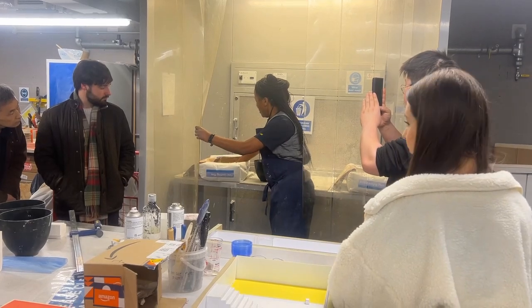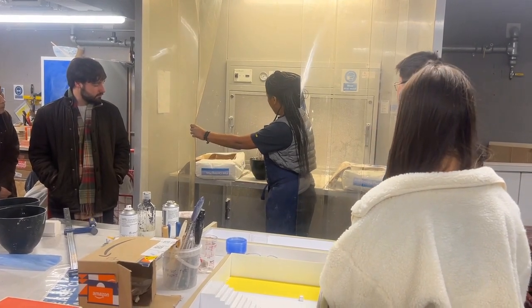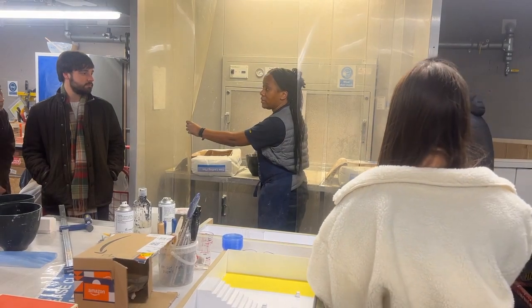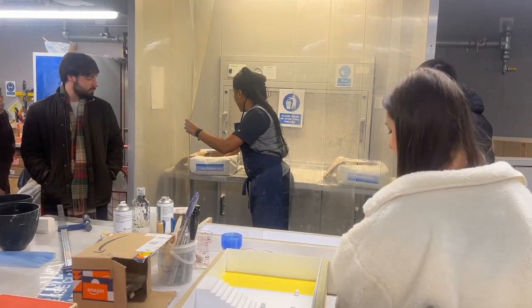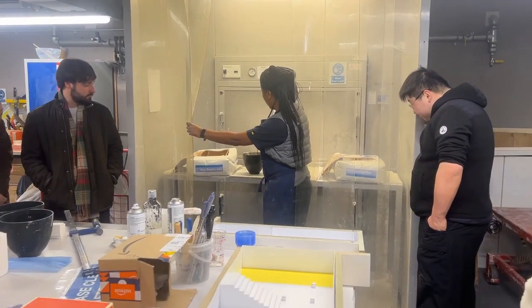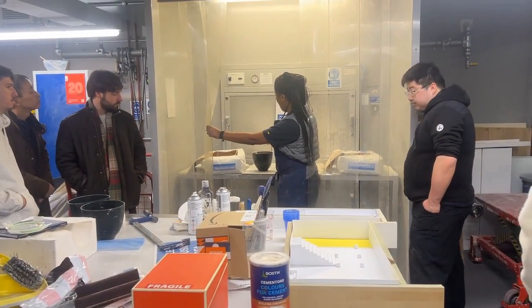So you just keep on going in a circular motion. And people always keep asking, how do you know? The plaster's going to tell me. So you keep on doing it, and at the moment the plaster is really absorbing the water, but it gets to the point where it starts to slow down.